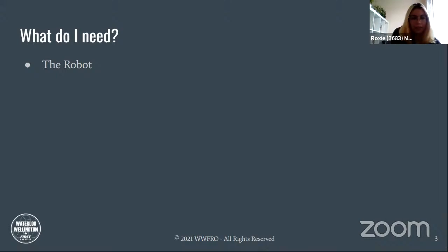So mine is unplugged, and I'm going to use a USB-B port to plug it directly into my Arduino board to upload code. You can also do that if you have a USB-B, but obviously you might not be prepared. So probably the best way, if you can, is the ESP module. I just didn't have time to debug why it's being finicky, so I'm going to go the old-fashioned way.